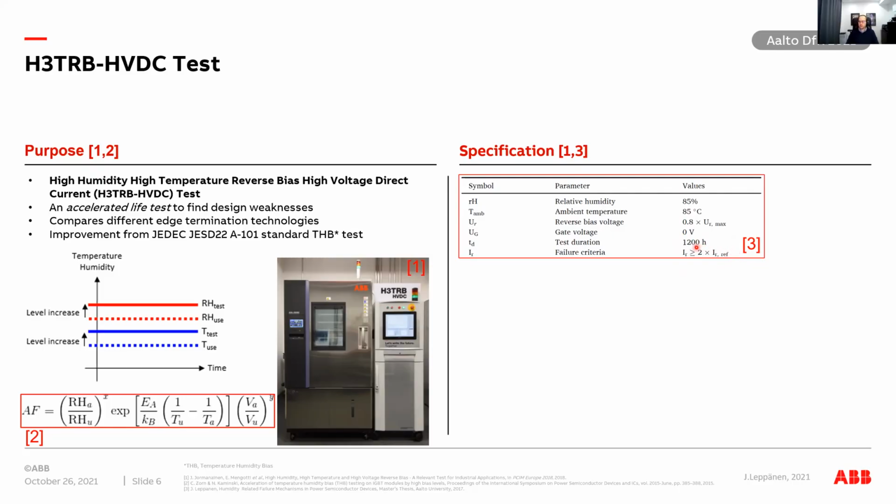It has to be reasonable. It just cannot be 1 ampere or 1 milliampere. It has to be somewhere in the range of tens, or at least less than 100 microamperes or something like that. And with silicon carbide and other wide bandgap semiconductors, it's an even lower level. And that's why we use this doubling of the reference.